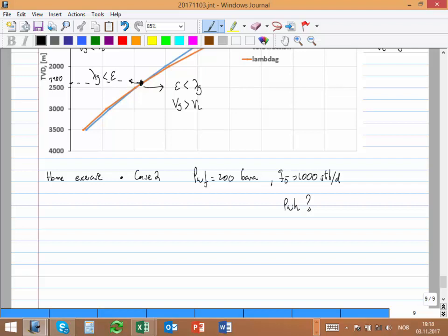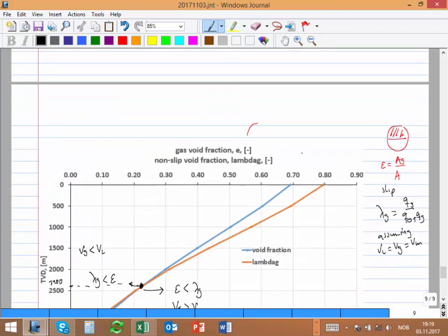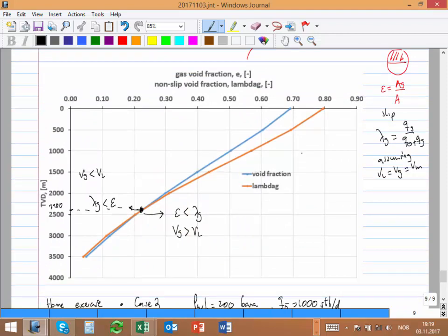Now, one question that maybe you will encounter: what happens if at a certain point the pressure that I calculate is negative? For example, here I calculate 100 bar, and then plus dp/dx times delta x gives me a negative number. The next point in the tubing is negative. Is it possible to produce this well or not? No, because I need a much lower pressure. In that case I have to increase the bottom hole pressure. But you won't find it, because we know this well is able to produce 1,000 if you have 180 right at the bottom.